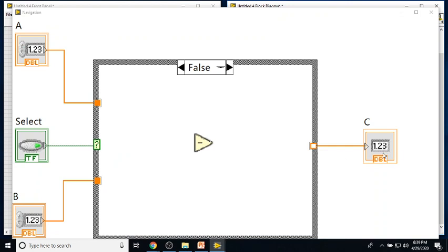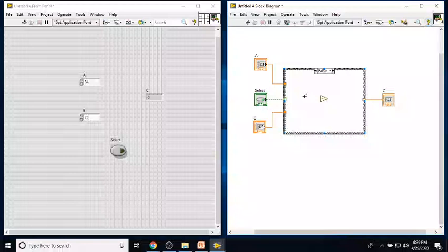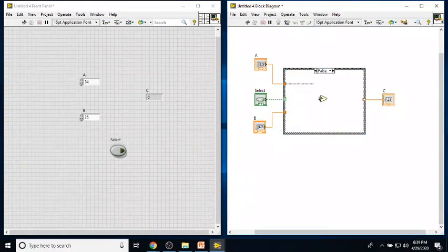So you should guide LabVIEW in such a way that it doesn't get stuck anywhere. So even if a true case executes, the tunnel should know what should be passing out. Even if the false case executes, it should know what data should be passing out, right? So you can see that when I connect it from here to here, right click, I'll clean up this wire, it's a bit messy. Yes, so I'll just connect it from here to here, right? Don't worry about the bendings of the wire, you can directly connect them. It is going to pass the data anyway.